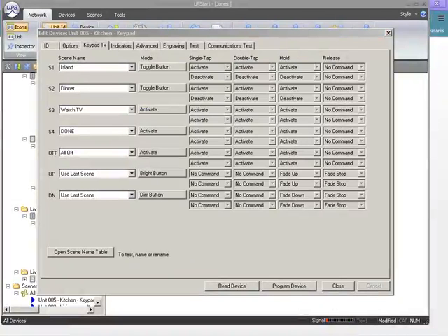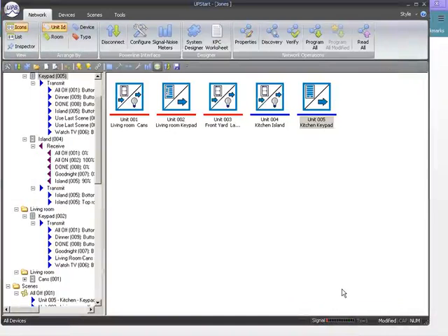The reality is I use a 1,000-watt switch on my transformer for my landscape lights, and I can actually dim my magnetic transformer with my 1,000-watt unit switch. So it actually changes the way everything looks. So scene one, I can turn on my light. I can do my toggle, and you can see that the up and down arrows are illuminating. So now I can dim and brighten that light itself.